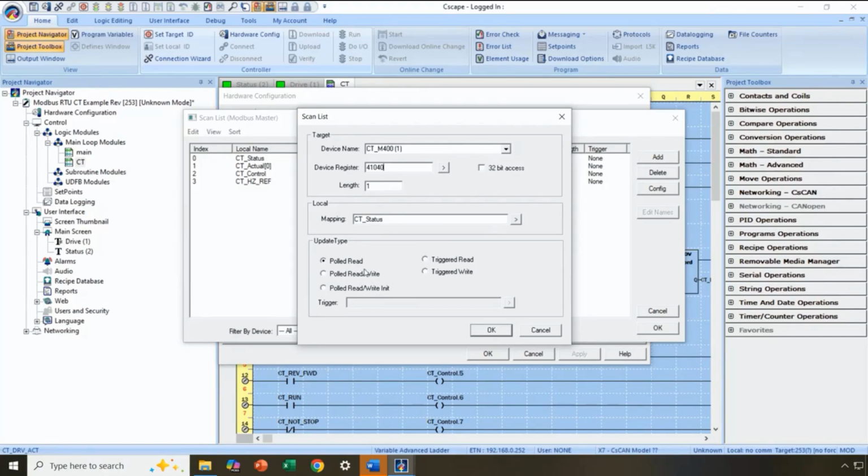If you have especially large lists for the data that you need to read or write, for some of them you might have to make them triggered so that they are not regularly part of the poll list. That will help you keep your scan rate down. So if there is data you do not care about getting frequent updates on, you can trigger it once a minute or once every few minutes to get a copy of the data.